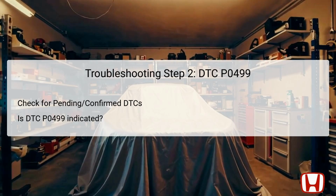If DTC P0499 is indicated, you will proceed to the next troubleshooting step. However, if it is not present, this suggests an intermittent failure, and you should inspect for poor connections or loose terminals at both the EVAP canister vent shut valve and the PCM.